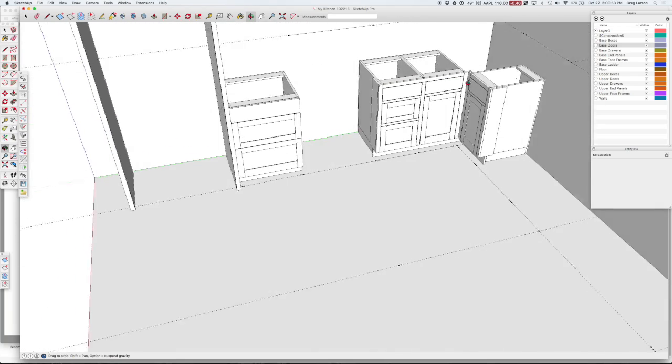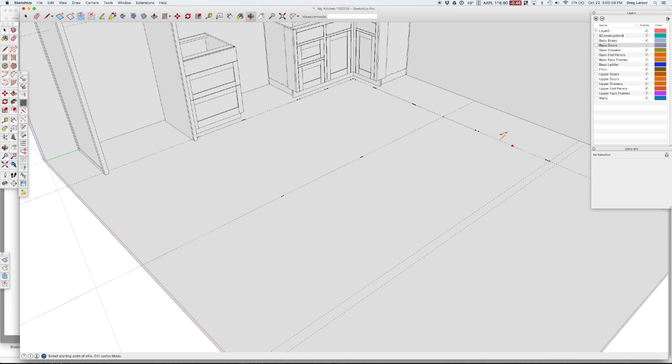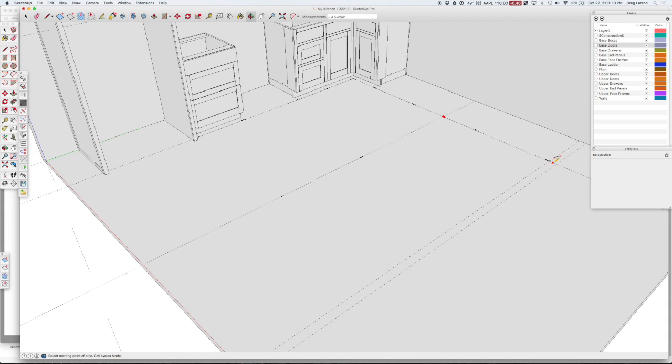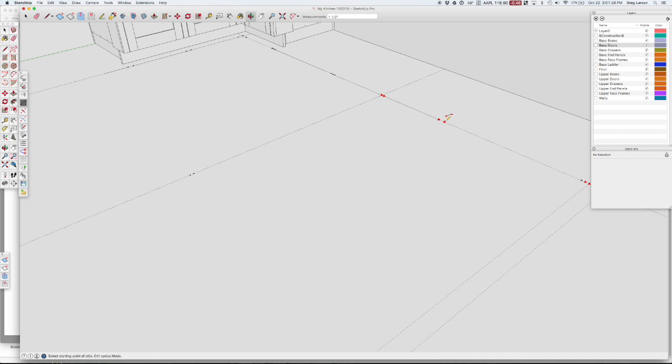Now, if I wanted to draw a frameless cabinet over here that had an opening on this side, left hand opening, and over here, I'm going to just draw it as a right end filler. I want it to be as generic as I can. And I'm going to still put a connector style in here. And notice it's still 1.5 inches wide. That's because there's 2 cabinet sides in there. So it's making the style as wide as that.